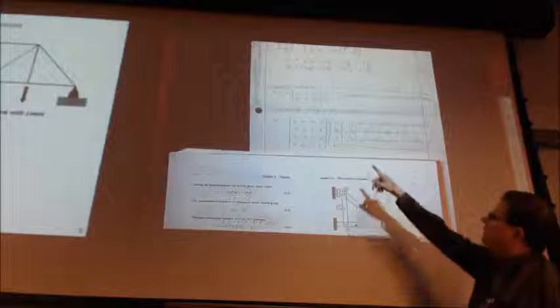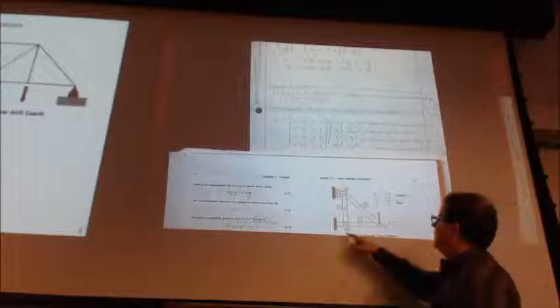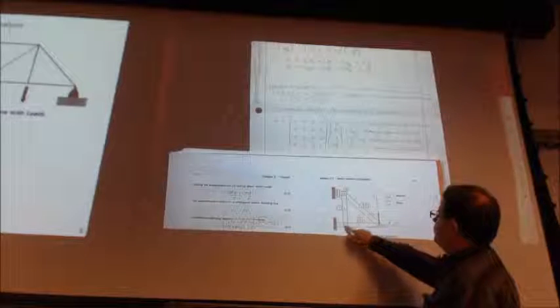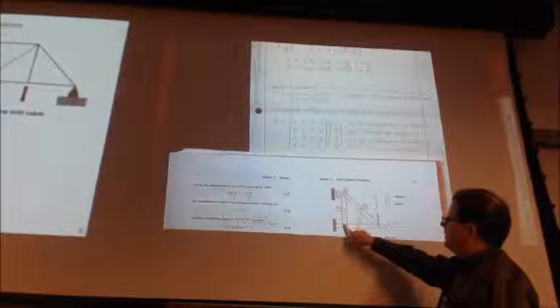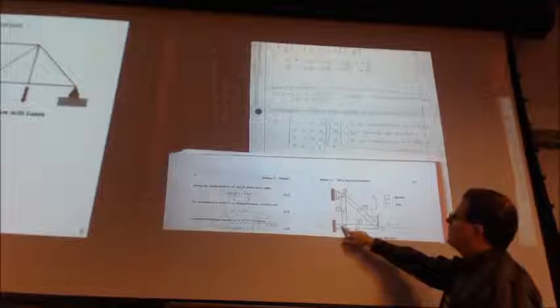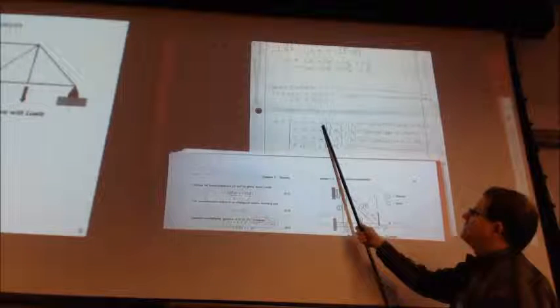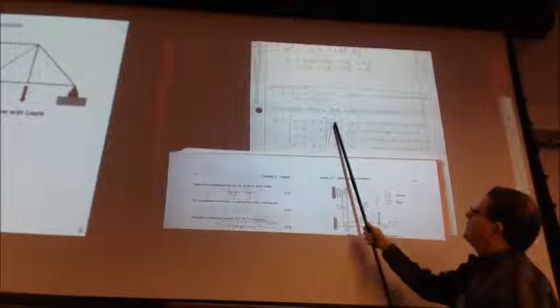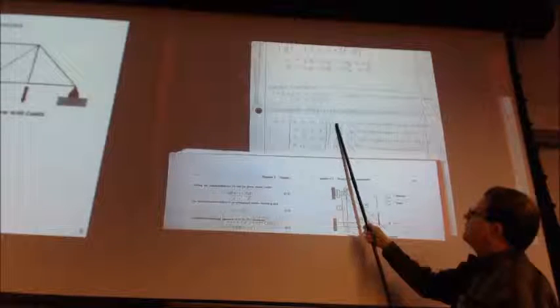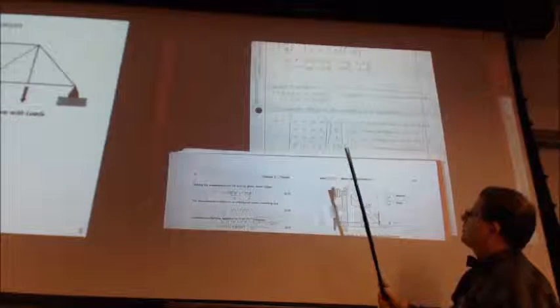and we're setting up our matrix, and we're on node 2, right? So this is our element. For this particular element, node 2, we don't have any X translation. So all of these are going to be 0. 0 for the U, 0 for the V, right?